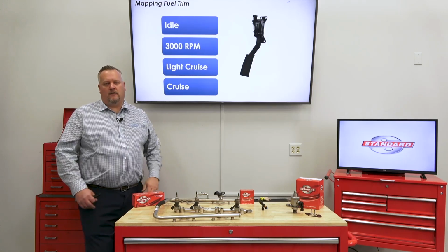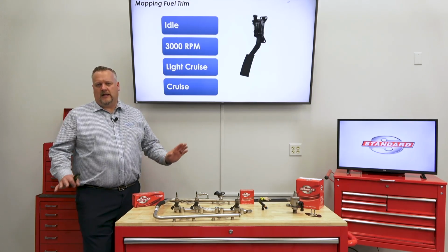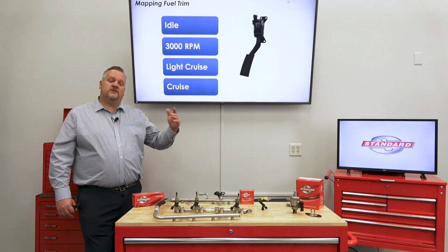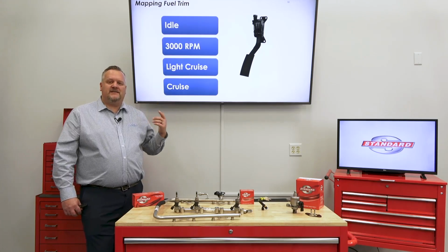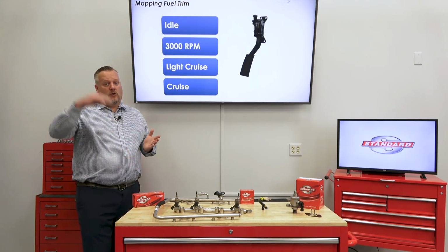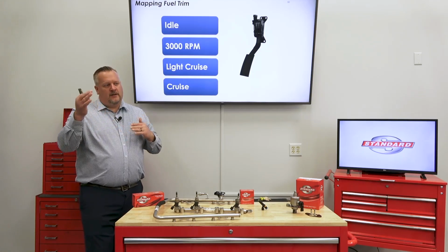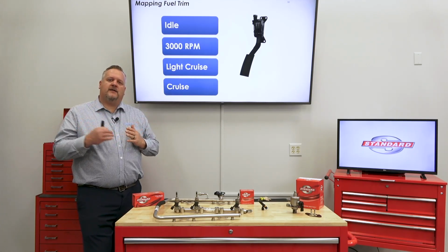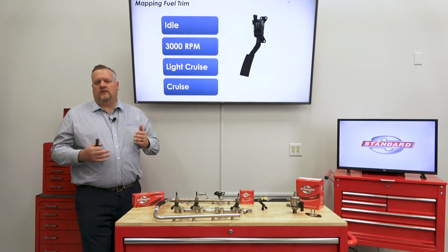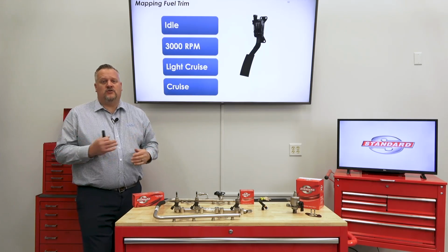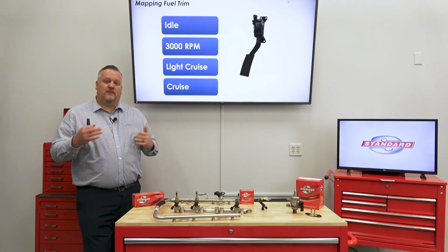In my area, I can go 55 miles an hour without a whole lot of traffic congestion. And so what is my trim doing there? Based on what's happening at idle or free revving the engine or during partial load, I'm going to look at how the fuel trims react. Through history and a lot of studying and knowledge, I very much understand what these patterns mean.